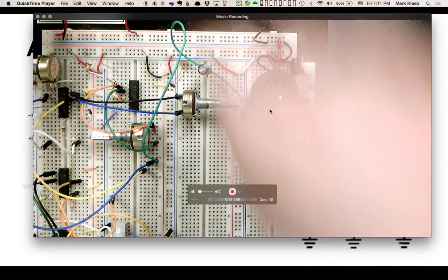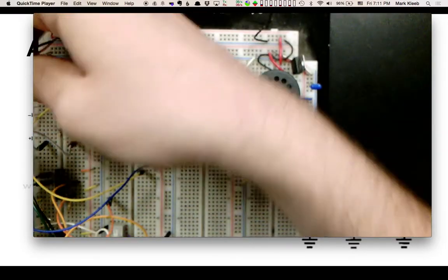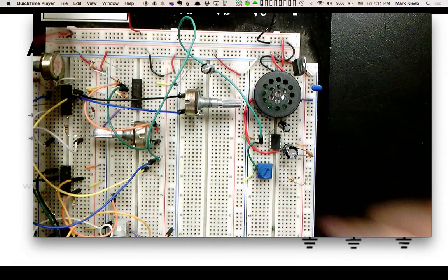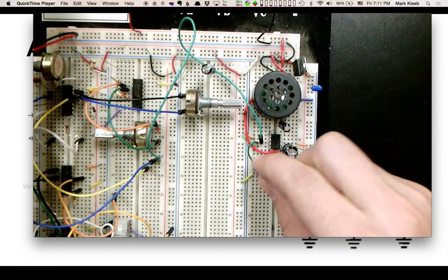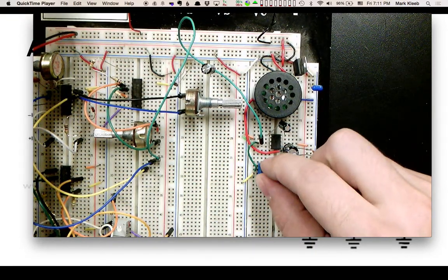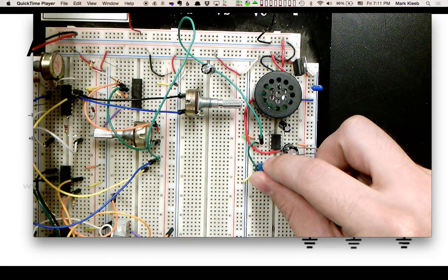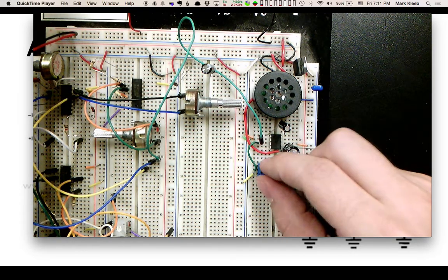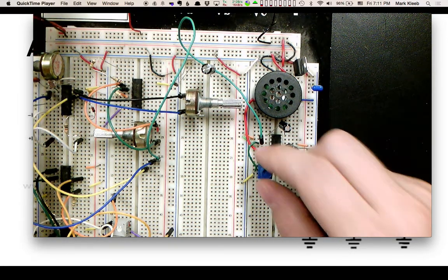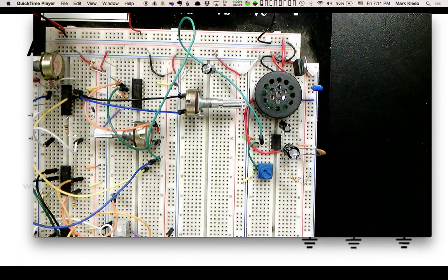I guess I can play this for you so you can see how loud it is. So it's a pretty steep volume cutoff, and this is because I'm using a linear tapered potentiometer, right? Now, in audio, because your ears hear volume logarithmically, with a linear tapered pot, you're not going to get a good roll off of volume.